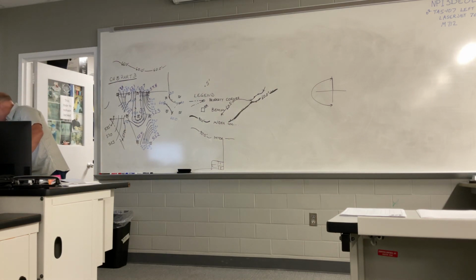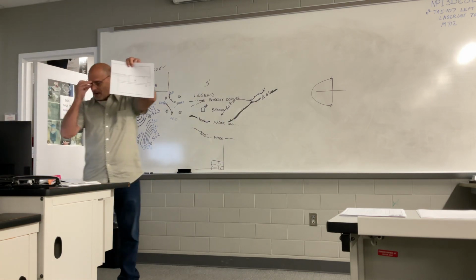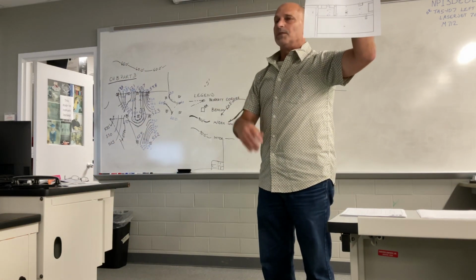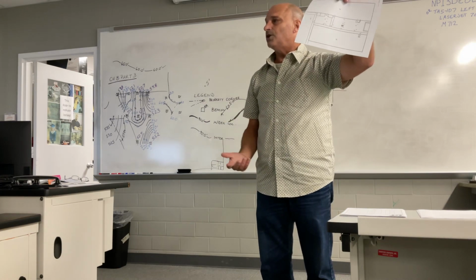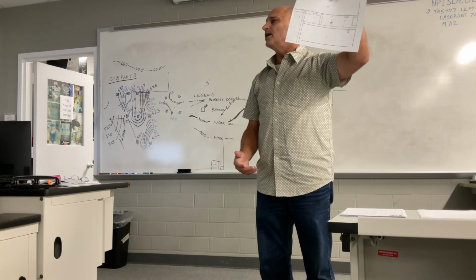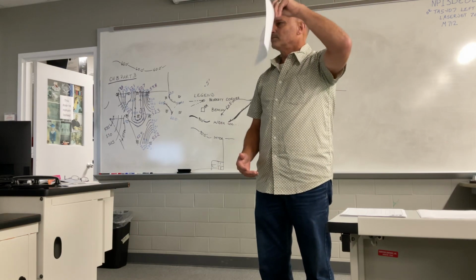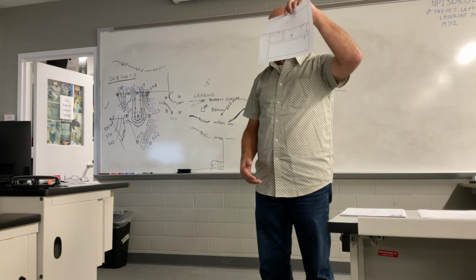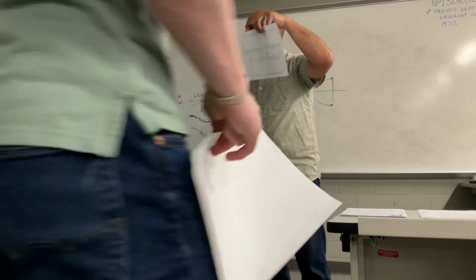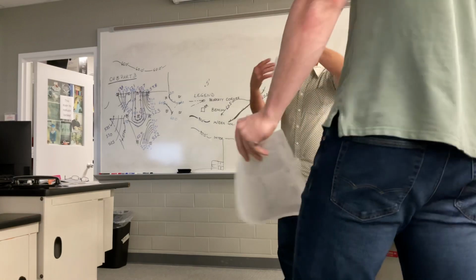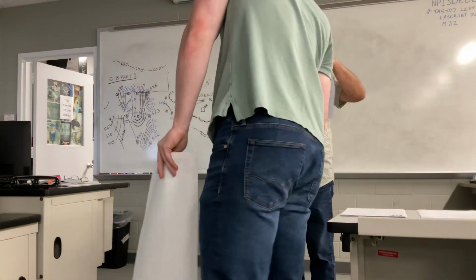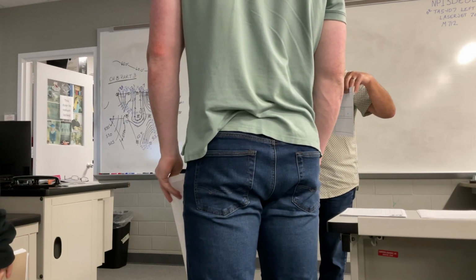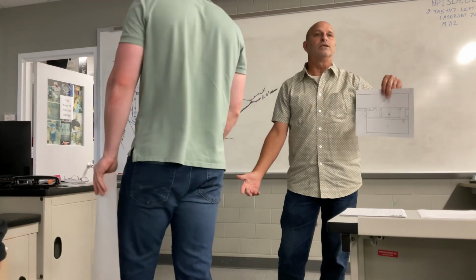Talk about your survey. Like I said, all you need is a printout of that area. You can do a snippet with the snipping tool and get a screenshot. You might want to turn that landscape style, because you're going to be writing on there and it's going to be hard to lay all that out. Just say landscape instead of portrait, because you're going to need room to write, maybe even 11 by 17. And remember, you really only need one person to go out and make these marks.